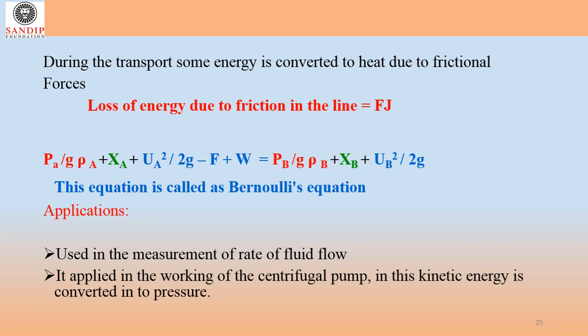So keep in mind for Bernoulli's theorem: the total sum of potential energy, pressure energy and kinetic energy, plus the energy added by the pump as W, and the loss of energy converted to heat due to frictional forces, that is minus F. This is all about Bernoulli's theorem.